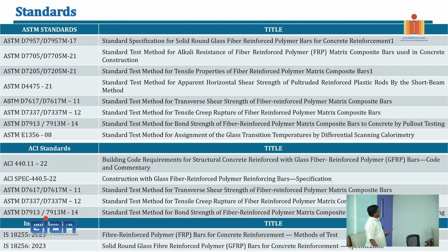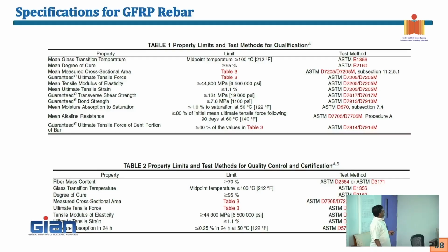I think Professor Gangarao already spoke about it. One thing that I really want to spend some time on is this. This is the most important thing: moisture absorption. The tendency of our manufacturers is to make it more cost effective and competitive, so they tend to add a lot of fillers. We have tested some bars and they are not really meeting the moisture absorption limit.